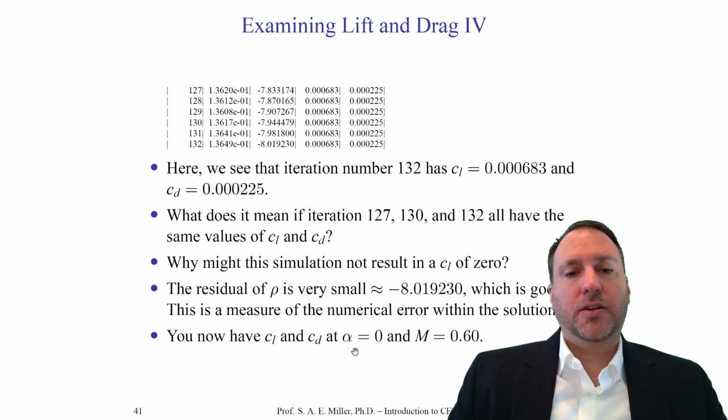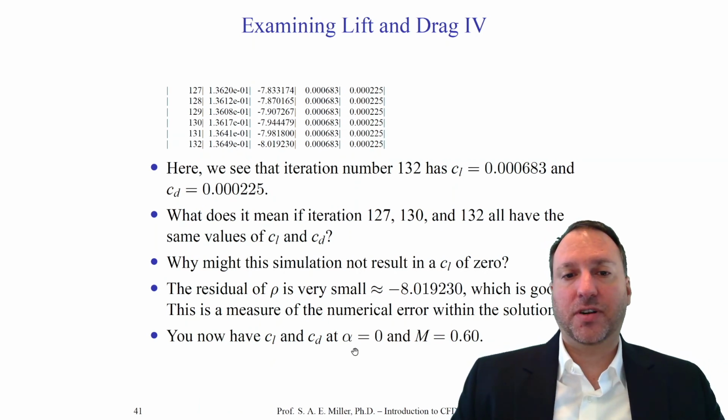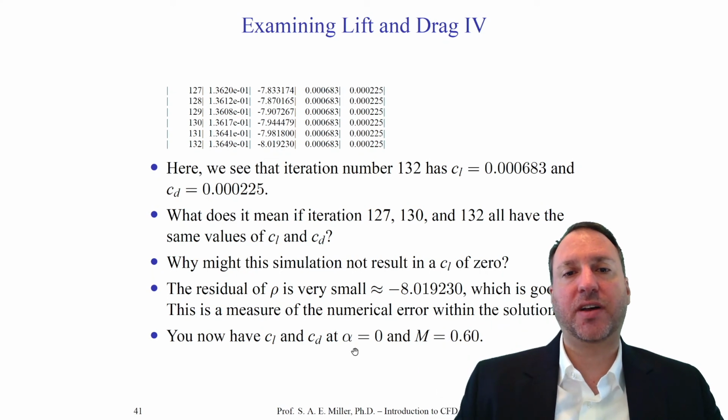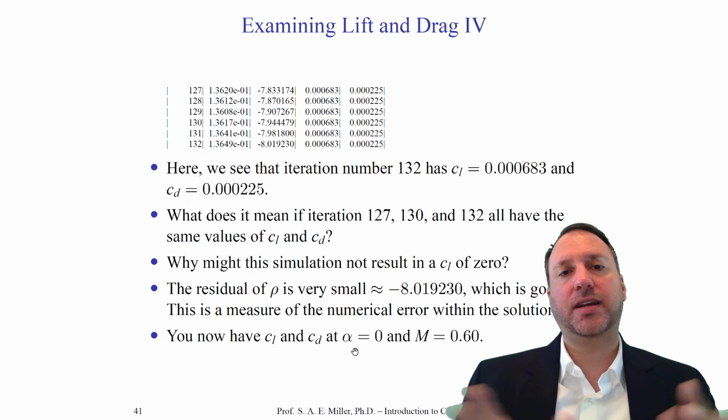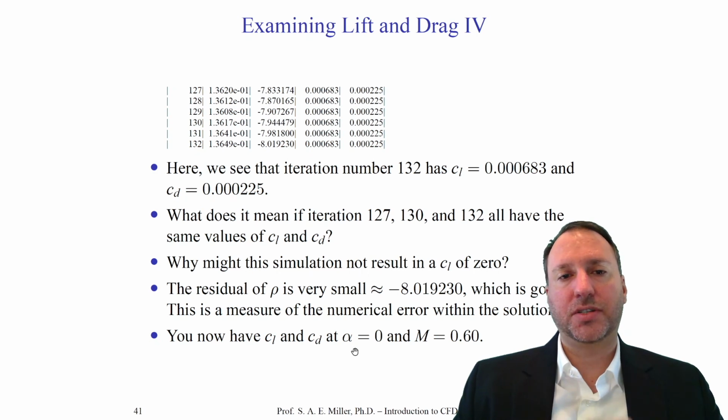You can also be free to change the angle of attack. Change the angle of attack to like 45 degrees, negative 10 degrees, 0 degrees. Experiment, run a few cases, and you'll get used to seeing the results. For every case, visualize both the contours of pressure, Mach number, etc., and also look at line plots of, of course, the coefficients of lift and drag. The more you try and experiment, the more you'll understand in the CFD code.